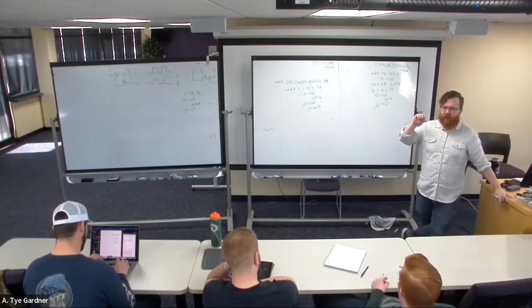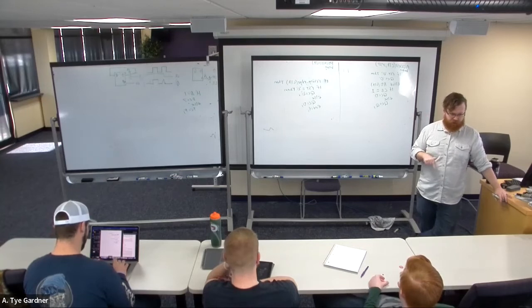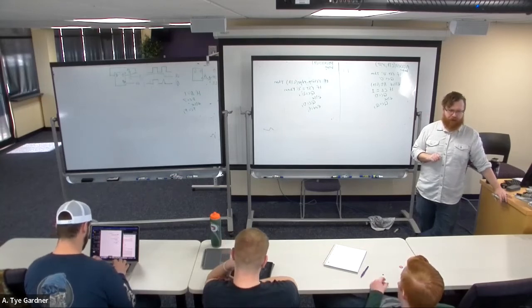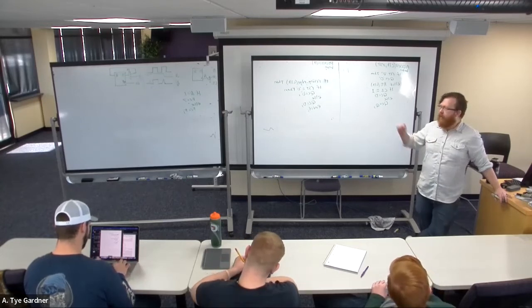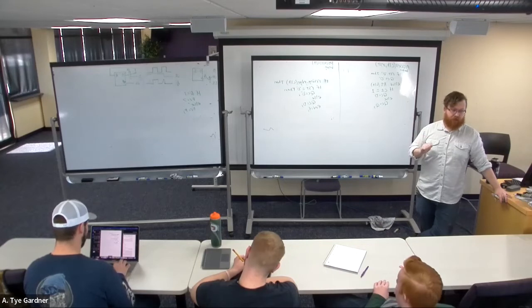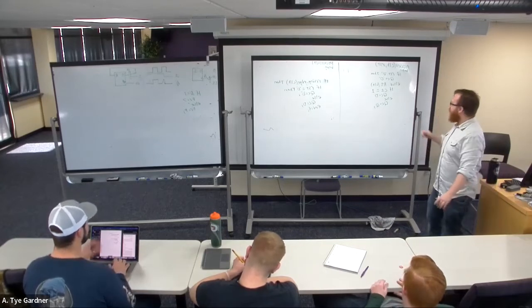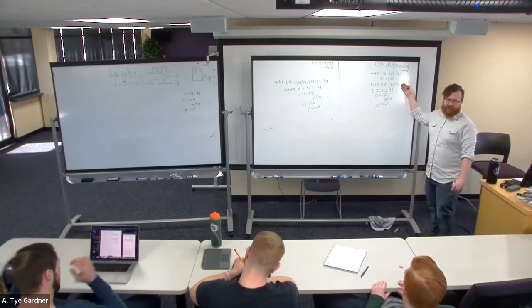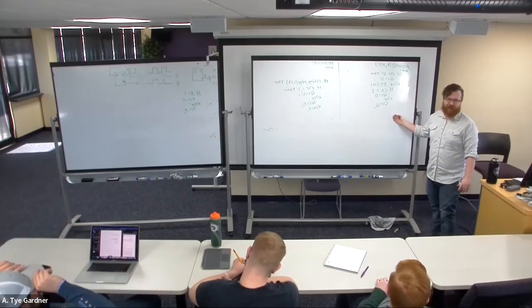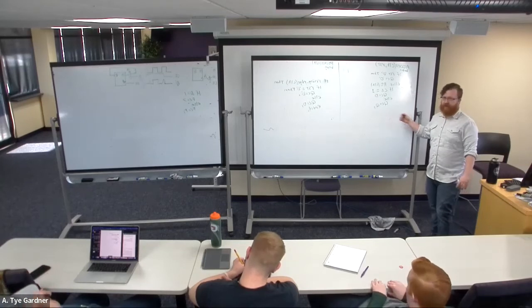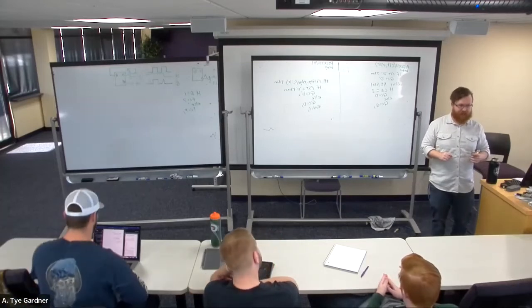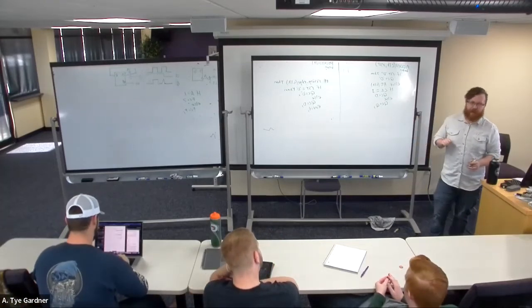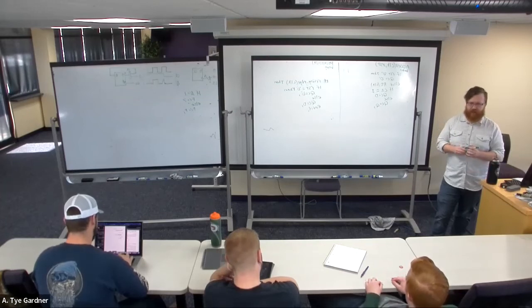I see these errors rarely in digital circuits in this class. I see them often pop up with actual issues in digital systems. So be aware that not having an else means don't care. I don't care what happens if I don't have that. In the case of the if reset else if rising edge of clock, you don't really need an else. It's fine. I've never seen this one go astray. I don't know, maybe I'll find something on the internet that tells me I've been wrong this whole time in my career, but I haven't seen it cause an issue. However, the if statements when I'm assigning signals, I've seen cause issues fairly often. So be aware.